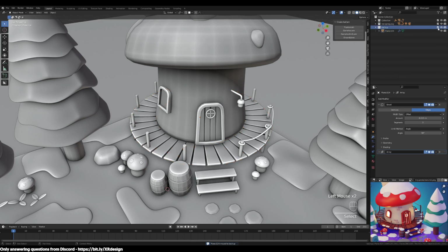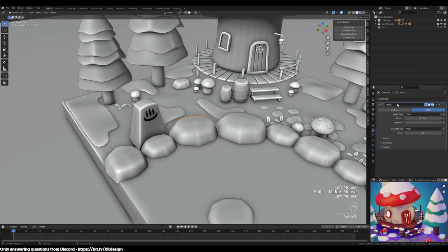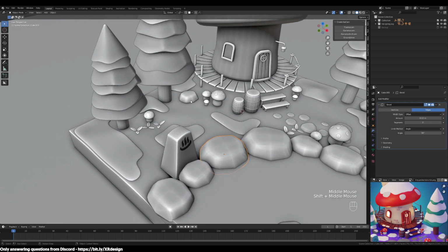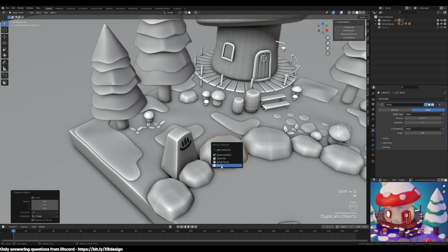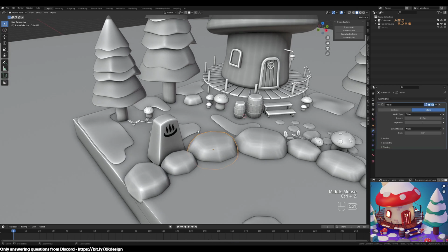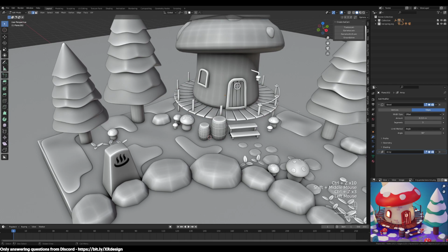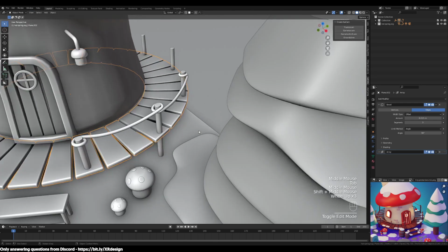And then this one, I would just deselect so that it's not showing in the scene. You're not able to edit that at all. So any of the modifiers that need to be applied, I just copy into this folder so that I don't have to worry about losing those objects. For now, I don't need to do that, but that is how you would do it.